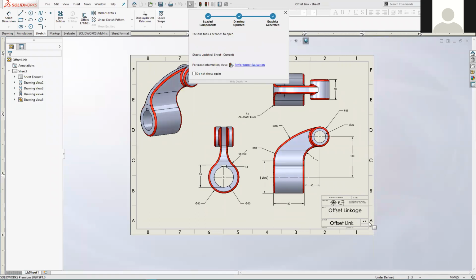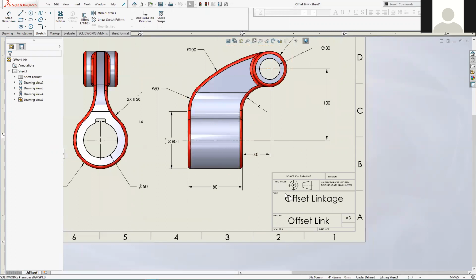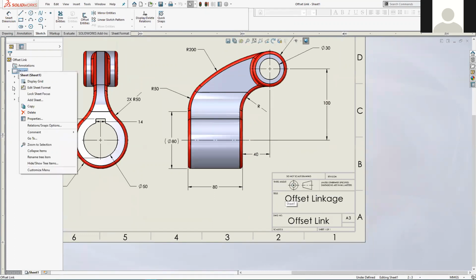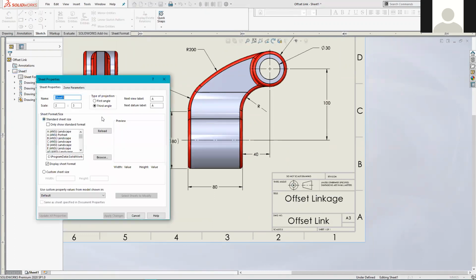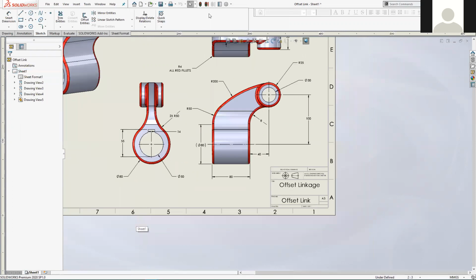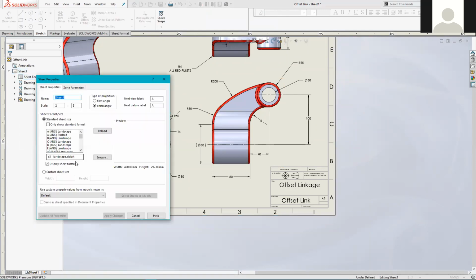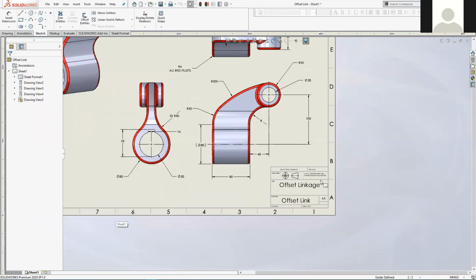This was one that I did with one of my other SolidWorks groups because we were using this example as well. You can see this one's already been edited, but what I'm about to do is put this back to the ANSI format that you will be looking at on yours. So it was ANSI A3, landscape, apply, maybe do a refresh. That's interesting. Try that again. Not updating.